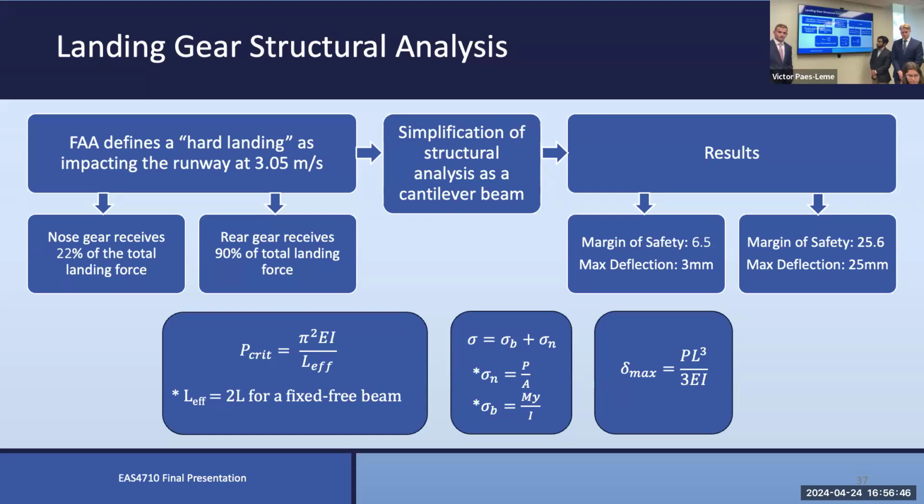Okay. So inherently, you're assuming something about the compliance of your airframe structure as you're doing that, right? Like your landing gear is going to compress, and the main gear is going to kind of spread, bow out. Your wings are going to droop a little bit, and so you're going to absorb that kinetic energy as you come down, and it's going to take you that long to absorb the kinetic energy, and that impulse then is what drives the acceleration. Okay.